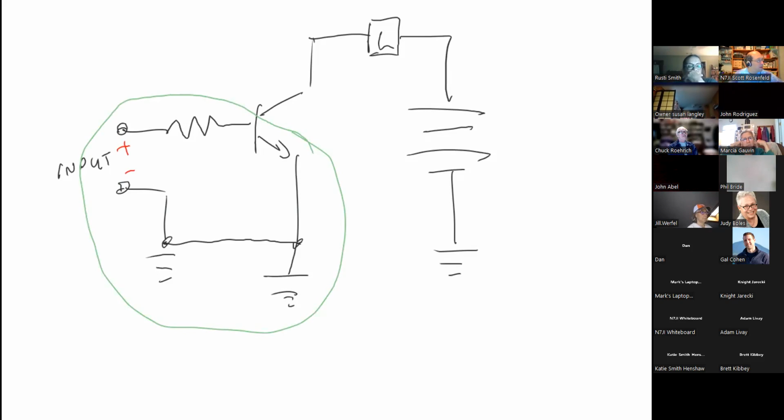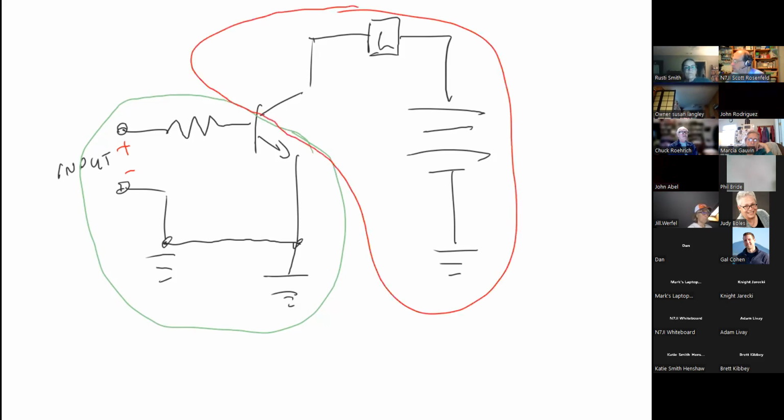So what we're saying in the diagram is that on the way to charging up the other battery, the light is going on. Yep. Basically because the transistor is essentially two halves. It's split into two pieces. There's the base to emitter junction, and there's the collector to emitter junction. It's really two pieces. If the base to emitter junction becomes active, the collector to emitter junction becomes really, really open.